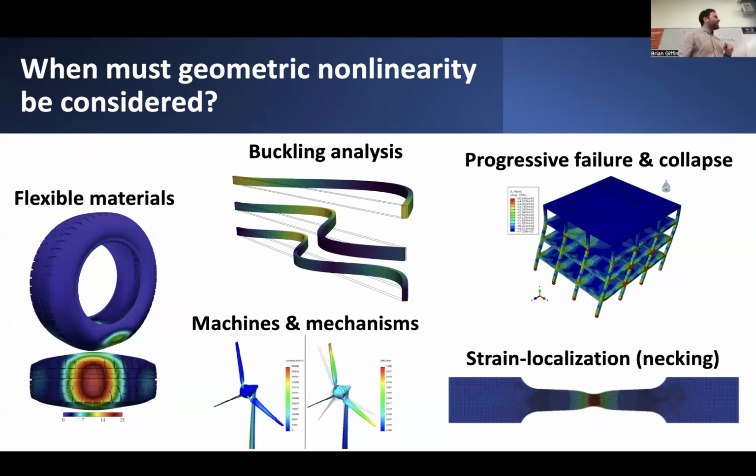And then the other one that we talked about last time: if you have elastoplastic necking problems or strain localization in some chunk of material, to represent that, and to represent the fact that the stress across the deformed cross-section of this necked specimen, because it's becoming smaller, technically speaking, should take into account the fact that the cross-section has decreased. That is effectively a geometrically nonlinear effect.